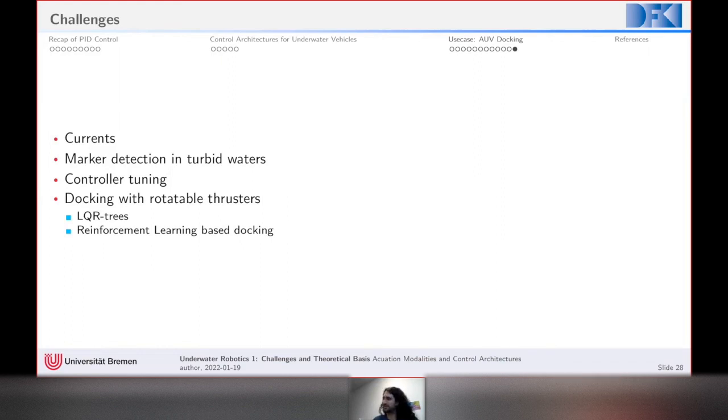I think also later on, Miguel is going to be talking about some other techniques that we're trying to experiment with, which is trying a magnetic sensor to measure the distortions caused by hard iron or soft iron that are present. For example, this docking station is just made out of steel, and if you have a magnetometer, whenever you get close to it, you can detect the distortion that this big metal thing does on the magnetic field of the Earth.